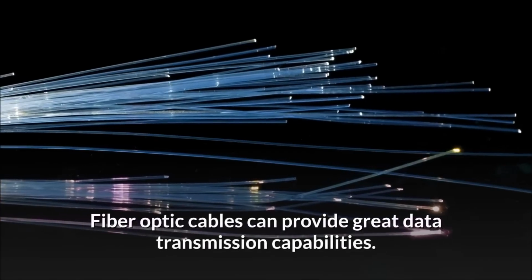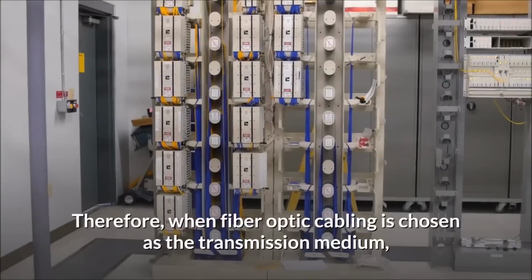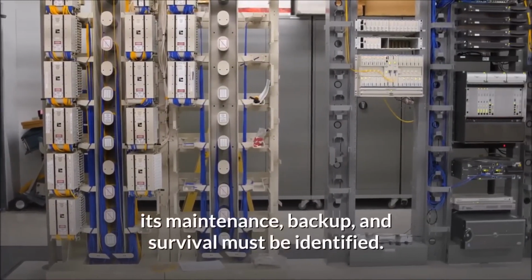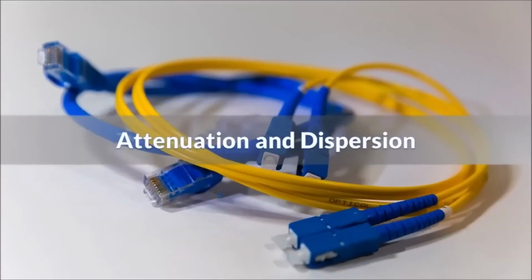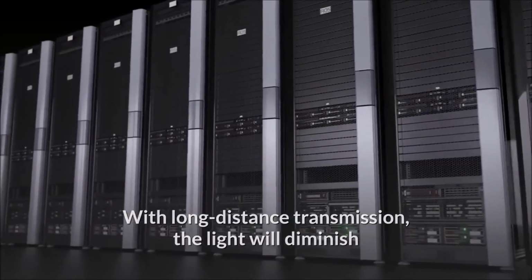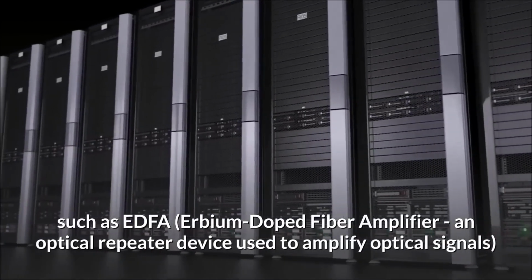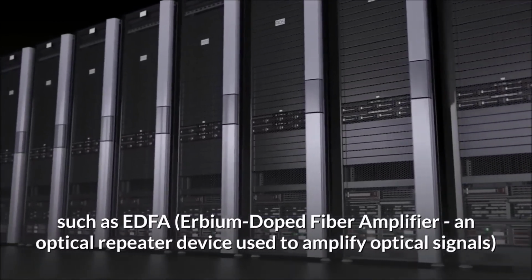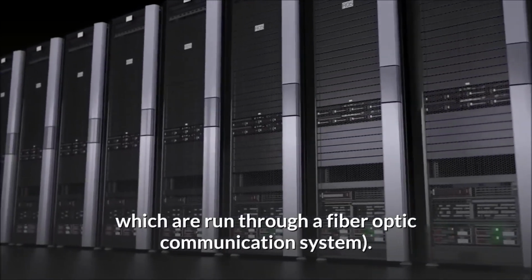Fiber optic cables can provide great data transmission capabilities. Therefore, when fiber optic cabling is chosen as the transmission medium, its maintenance, backup, and survival must be identified. Attenuation and dispersion. With long-distance transmission, the light will diminish and scatter, which means additional components such as EDFA, erbium-doped fiber amplifier, an optical repeater device used to amplify optical signals, are run through a fiber optic communication system.